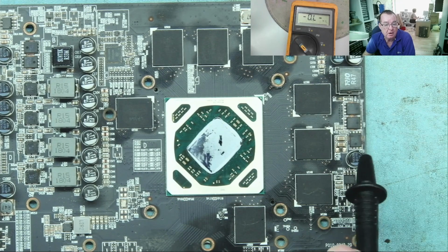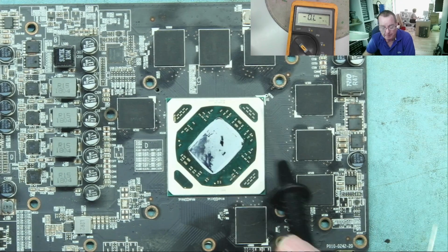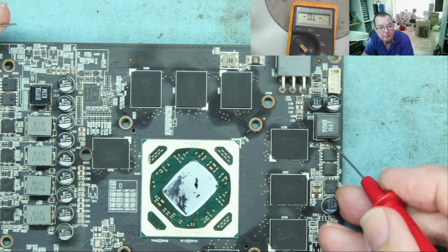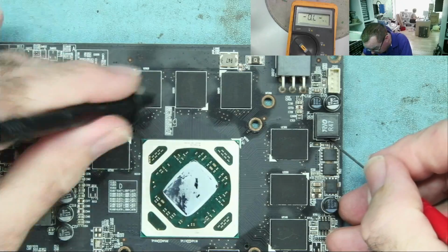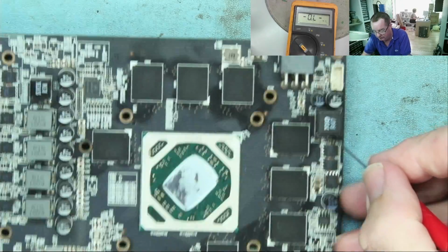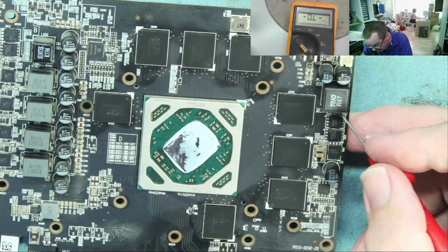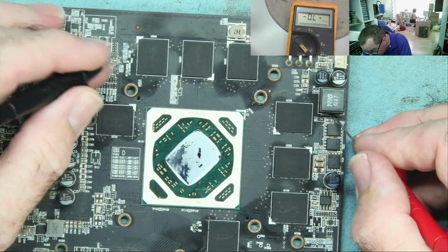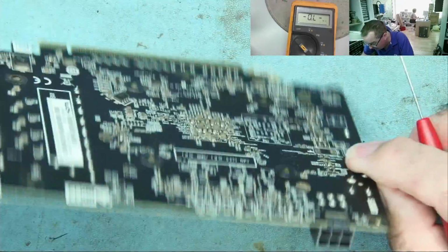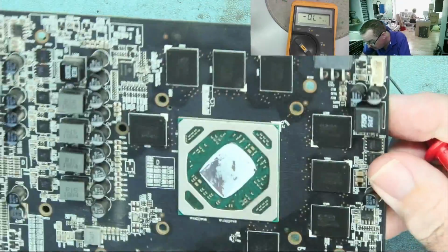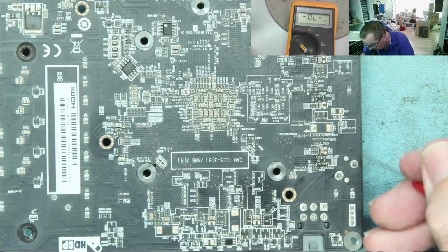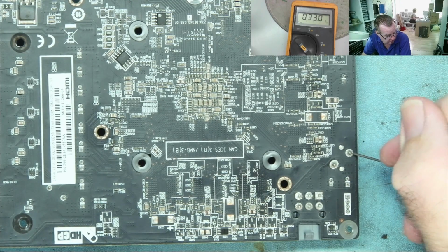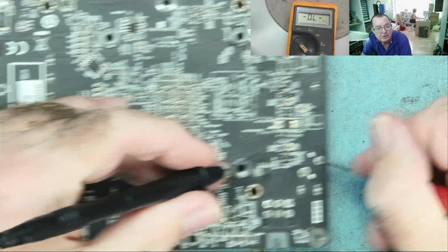Okay, if you want to know which one goes to the RAM, by the way, the easiest way to find out is to go from the supply and look for capacitors right by the RAM chips. Okay, if you can see any and we can find the voltage down here right by the RAM chips, then that is probably what it's applying. Let's have a look. Actually, we can get on this side of this one. Yeah, 33. So you can see where the RAM chips are.